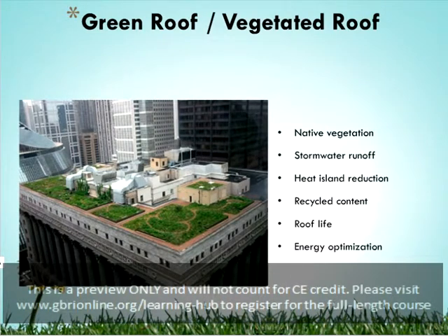Green roofs can be heavy, so designers should make sure to account for the extra weight when designing roof structures. When planted with native or adaptive species, the roofs should not need much more water than they will be able to absorb from rains, but there is still a bit more maintenance involved with a green roof than a traditional one. By preventing the rainwater that falls on a roof from flowing to ground level, projects can reduce the stress on other stormwater management interventions.